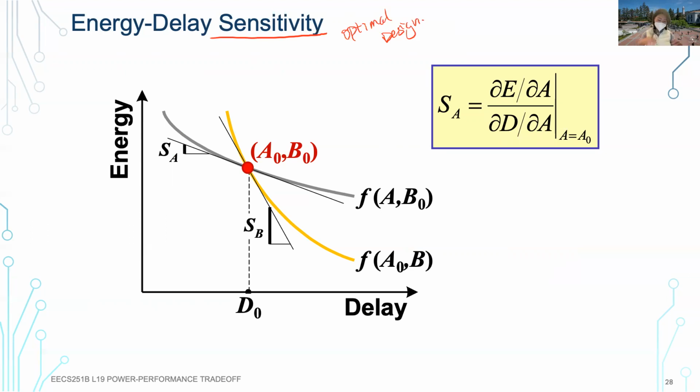Like we mentioned earlier, we were just focusing on the circuit level, right? So we can do VDD as one of the parameters, and another parameter, let's do sizing, right? So that's the things we're going to cover next. Those are the parameters that we have in this space. We can keep a fixed VDD and then change sizing, or we can keep a fixed sizing and then change VDD, right? So you will start from a particular point, and how would we navigate this space?